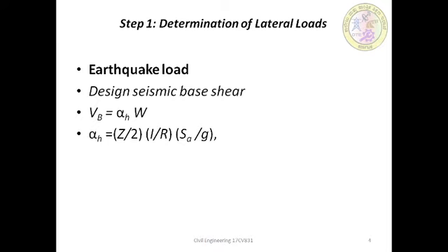Here the following are the major steps. The first one is determination of the base shear, and the next one is vertical distribution of the base shear to the different floors. So let us see how the base shear is to be calculated.